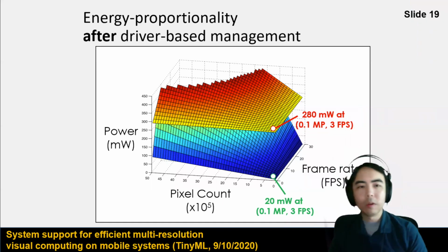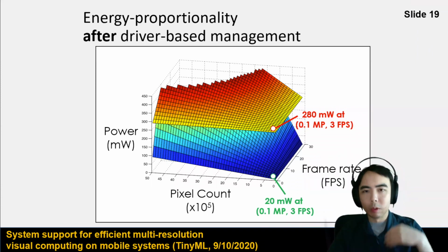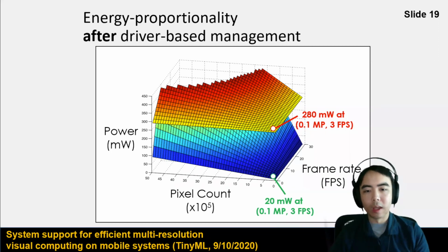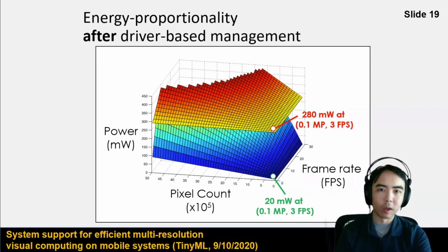Yes, so if you're operating at a very high frame rate and a high resolution, you don't actually have the opportunity to throw away that idle power anymore, because your exposure time may be long enough that you need to have the sensor on while you are reading out other frames. It's the beauty of the rolling shutter architectures, or the global shutter architectures as well, that you're able to read out while you are exposing your frames. But the timing of being able to expose while reading out is important in those cases.